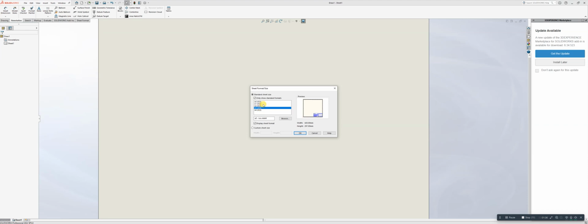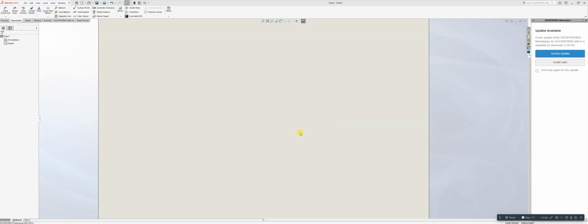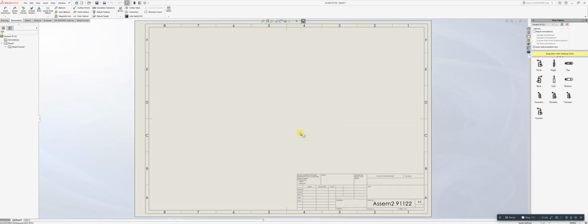You must remember, never ever do a drawing to a scale. Always draw 1:1 on that. I'll explain that in a second a little bit clearer. So I'm just going to press the OK, and then what should come up on my right hand side, where the drawing number is, it's actually put in the actual file name of that assembly. I can change that according to whatever I need to do.